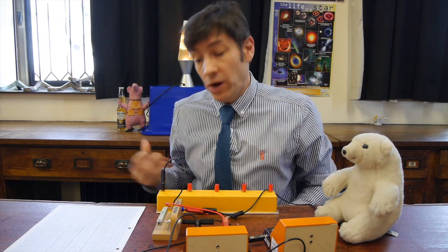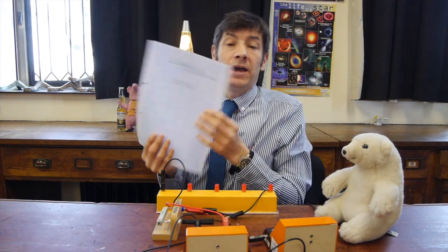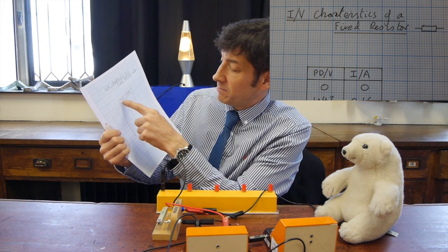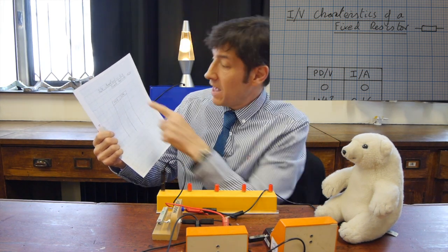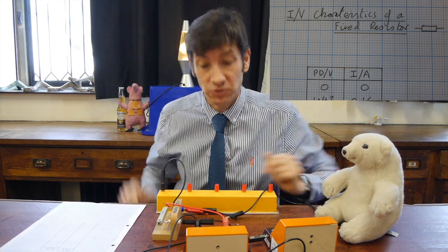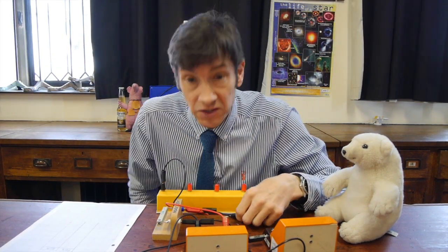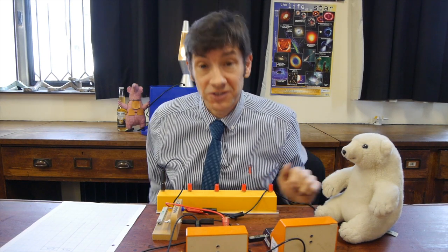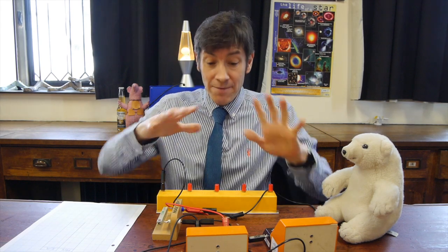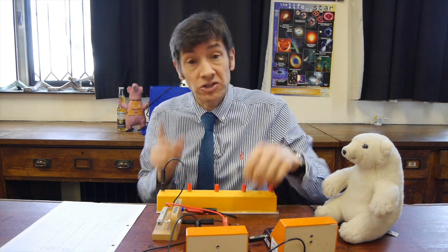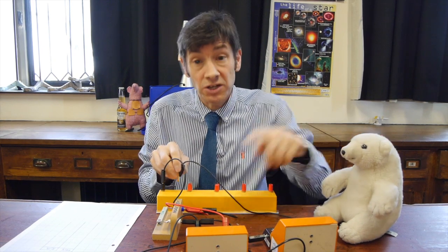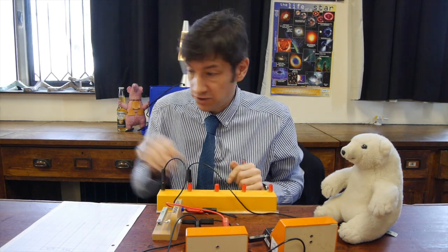So we're ready to go. I've drawn myself a little table here, and I'll put a photograph of that up. And it's pretty simple really. I'm measuring the potential difference with a voltmeter, and I'm measuring the current through the fixed resistor for different potential differences. So I've got my circuit here, and the trouble with circuits is they always look like snakes playing Twister, but don't worry too much about this. I'll just do a first reading, and I'm not reading off the battery. I'm actually using a voltmeter to read the potential difference.